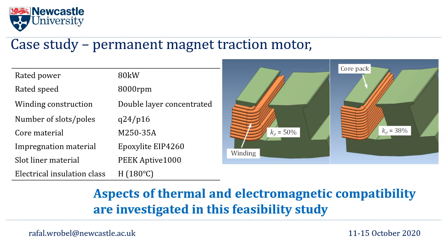The purpose of this analysis is to evaluate potential benefits and also limitations of employing heat pipes in thermal management, with focus on the stator winding assembly, looking into compatibility issues associated with additional loss or thermal heat transfer across multiple sub-assemblies.